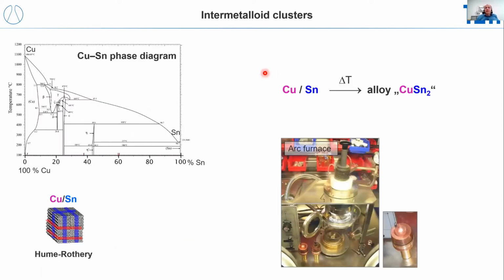So the way we make intermetallic compounds is that we study phase diagrams. Here we have 100% tin on the right side, 100% copper on the left side, and in between, this is a complex phase diagram, we see all those copper tin phases. Actually, to make a nice sounding bell, you have to go through the phase diagram in this area, which is rather complicated. Nevertheless, there are many compounds, they already have related structures, they are close packed, they are so-called Hume-Rothery phases, and you can make them easily.